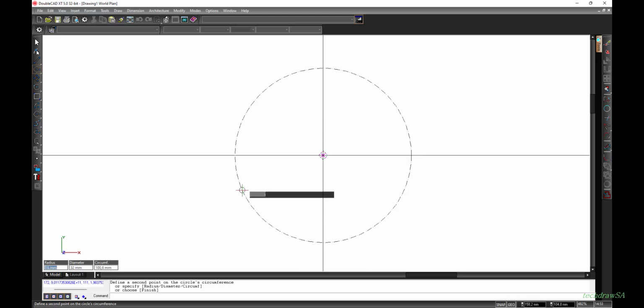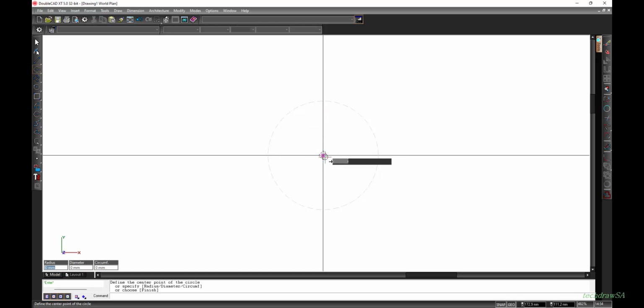In order to type in what you need, you can press tab and it will jump to the circumference, the radius, the diameter, or whatever you want. If you tab past circumference and keep on tabbing, be careful, and once you've tabbed about 2 or 3 times extra, you will come back to radius. That's where I want to be. So I'm going to tell it I want a radius of 10 millimeters, and I'm just typing that in and pressing enter. Now the circle construction is exactly 10 millimeters from the intersection of the X, Y, and Z axis.